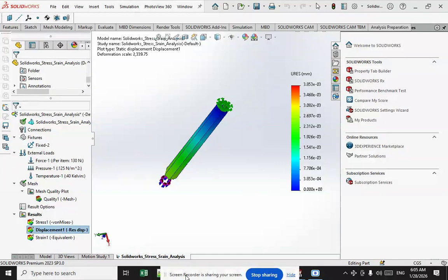An aircraft wing might be designed with a factor of safety of 1.25 on the yield strength of the wing and a factor of safety of 1.5 on its ultimate strength. The test fixtures that apply those loads to the wing during the test might be designed with a factor of safety of 3 on the ultimate strength, while the structure that shelters the test fixture might have an ultimate factor of safety of 10.